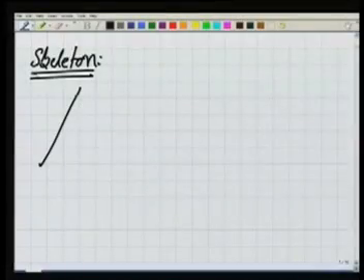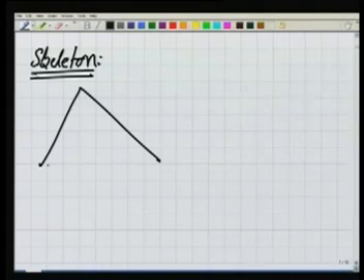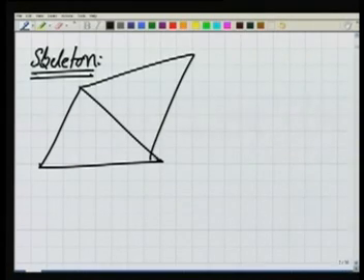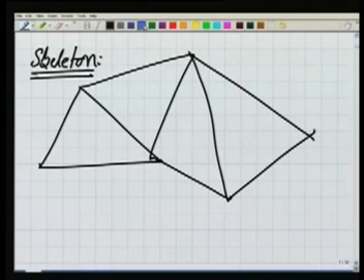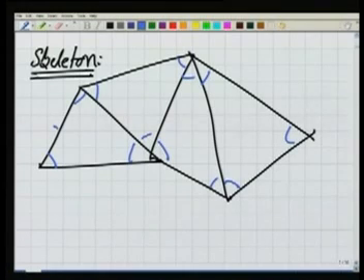Okay, now we'll see, because we are saying the triangulation is we measure one length, which is the base length, and then later on we measure the angles. For example, in this figure, all these angles are measured, as well as the length, the base length, only one length. Having done this, we will have the coordinates of all these points, so we are able to establish a network, a skeleton of the area.